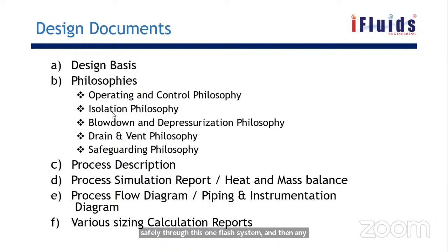And then the safeguarding philosophy. Here we have talked about the interlocks, right? Similarly, in case of overpressure, we will have a pressure transmitter and we will stop the system. If that pressure transmitter fails, then we will have a mechanical device. Those things will be captured in the safeguarding philosophy, how we need to consider all those things.